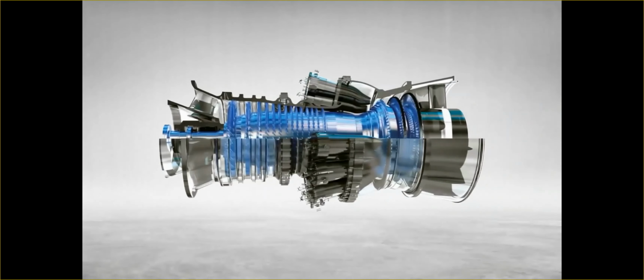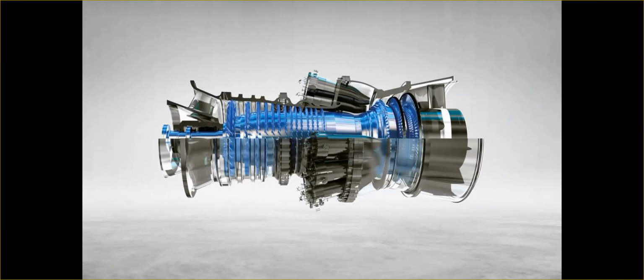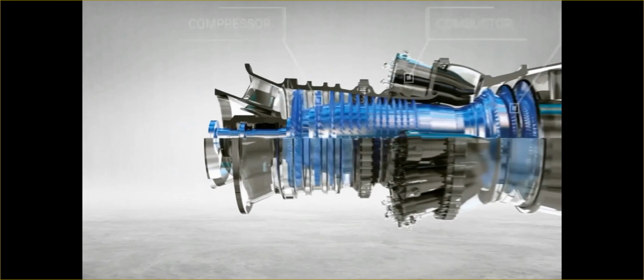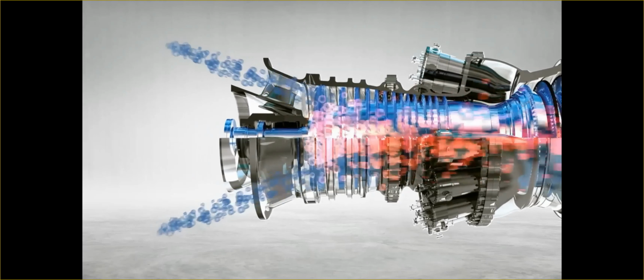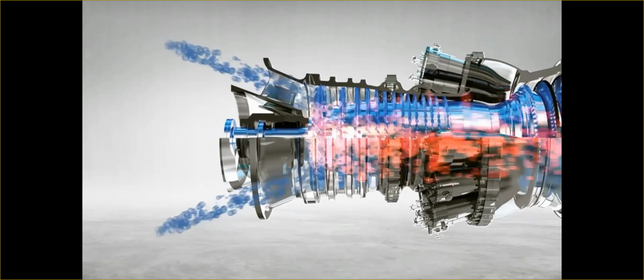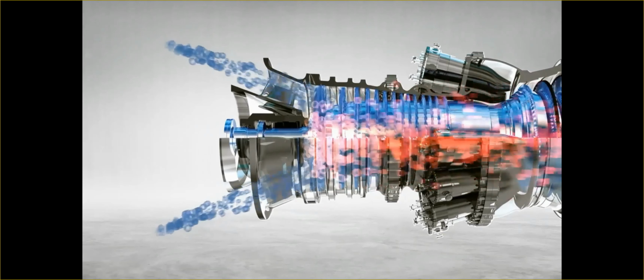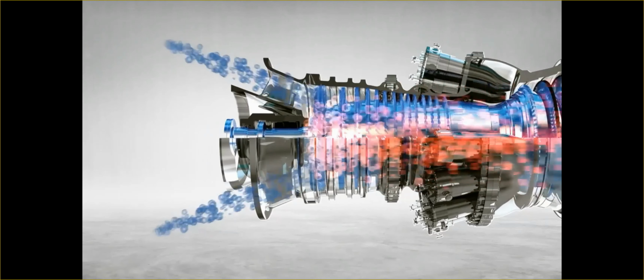A gas turbine usually consists of three main parts: compressor, combustor, and turbine. At first, the air is drawn inside the compressor. Inside the compressor, the air is squeezed, similar to a tire pump that squeezes air inside the tire, while the air's pressure and temperature rise. Then it enters the combustor. In the combustor, the fuel is injected into the air, and its combustion produces a lot of energy and increases the air pressure and temperature remarkably. This is similar to what happens inside a car's engine.